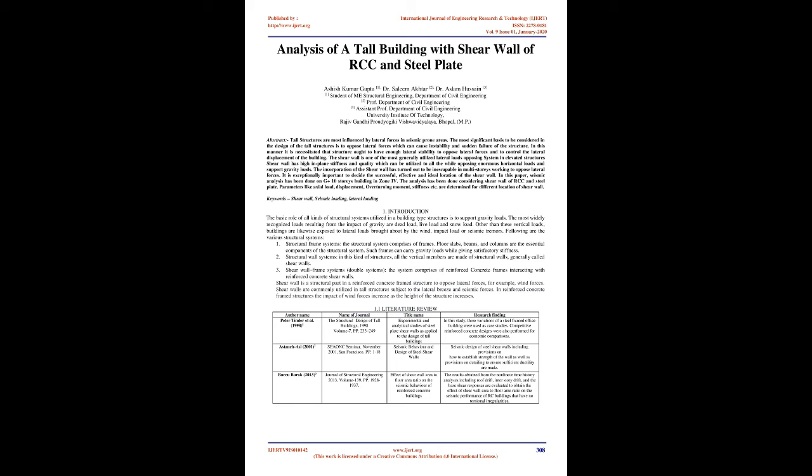and support gravity loads. The incorporation of the shear wall has turned out to be inescapable in multi-storey buildings to oppose lateral forces. It is exceptionally important to decide the successful, effective, and ideal location of the shear wall. In this paper, seismic analysis has been done on a G+10 storey building in Zone 4. The analysis has been done considering shear wall of RCC and steel plate.